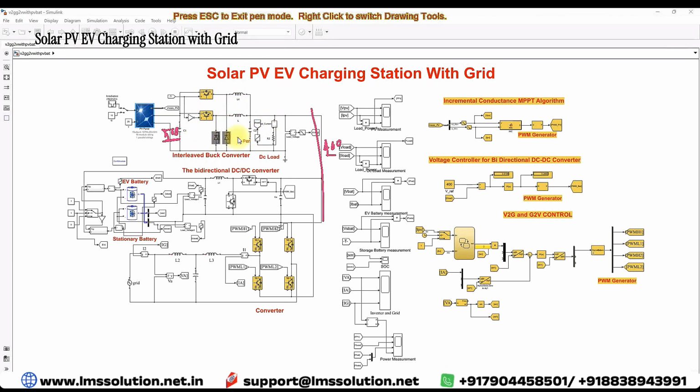Why are we using an interleaved buck converter? When we use a normal buck converter, it may go into discontinuous conduction mode, and also the ripple in the load current, the output of the converter and the input current is higher. In order to minimize that ripple current, here we are using an interleaved buck converter. When two converters are interleaved, the ripple of current is reduced. For that purpose only, we are using this interleaved buck converter.